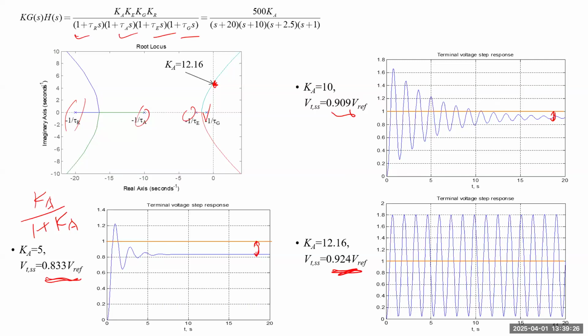Those 4 poles together determine each individual root locus. So we pay attention to the root locus that can intersect with the imaginary axis, for example, this one or that one. We don't worry about anything else. The others may change the time performance, but they don't change the stability of this system. So we only need to identify those 2. Now we know for this system, if the gain is around 12, the system is going to lose stability